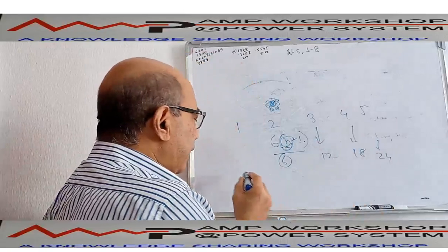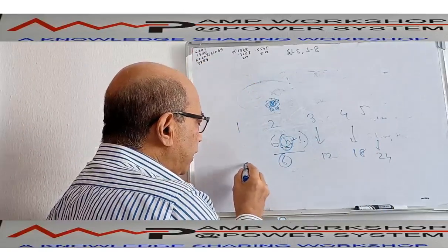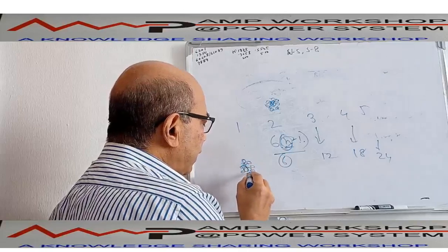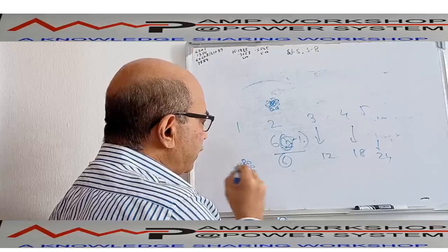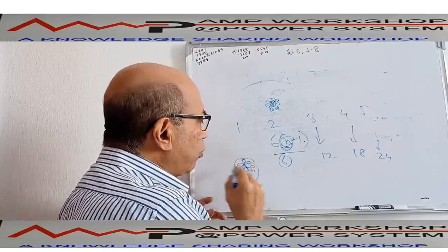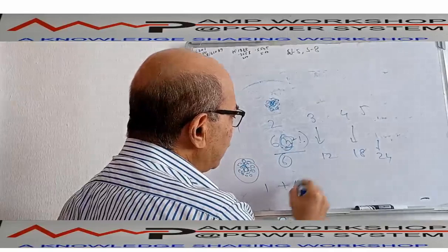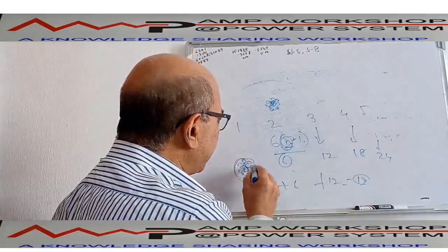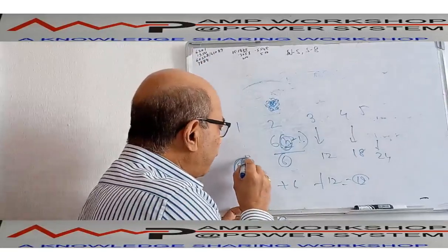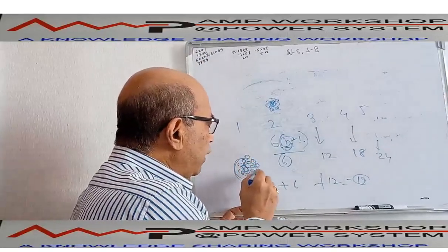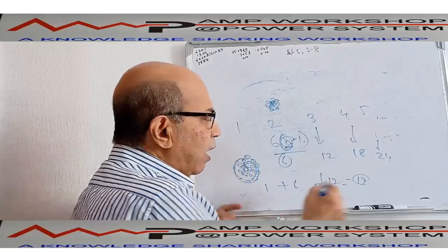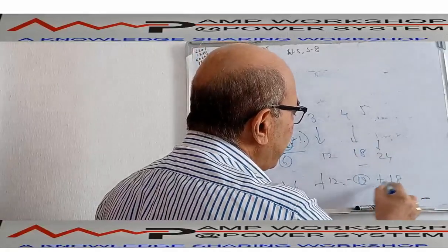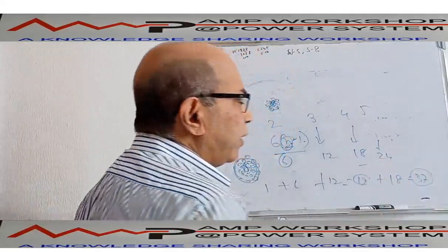So if we have a center conductor, layer 1, then a second level, then a third level conductor, this is a three-layer strand. How many total conductors will there be? First is 1, plus 6, plus the third layer 12. So the total will be 19 conductors. If I have a main conductor with 4 layers of strands like this, then how many? This will be 19 plus the fourth level, which is 18. 19 plus 18 means 37. There will be 37 conductors like this.